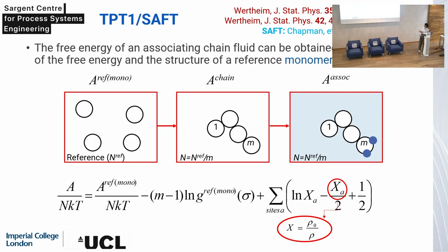Maybe I will not go too much through the technical details. I show for you the equation just to show you that it's surprisingly compact. Of course, this is for a pure compound. When you treat mixtures, the expressions are slightly larger, but they're just summations of components. Okay, and we write SAFT as an equation of state always in terms of the Helmholtz free energy, A. From the Helmholtz free energy through partial derivatives, you have all the thermodynamic properties, including derivative properties like heat capacities that are, for example, important again in the context of CO2 capture when you're doing your energy calculations.